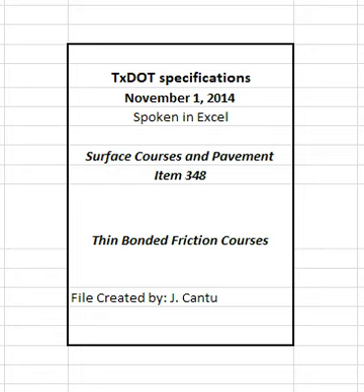4.4.2.2.4 Ignition oven correction factors. The engineer will use the split samples provided by the contractor to determine the aggregate and asphalt correction factors for the ignition oven used for quality assurance testing during production in accordance with Tex-236-F. The engineer will verify that the asphalt content correction factor takes into account the percent fibers in the mixture so that the fibers are excluded from the binder content determination.